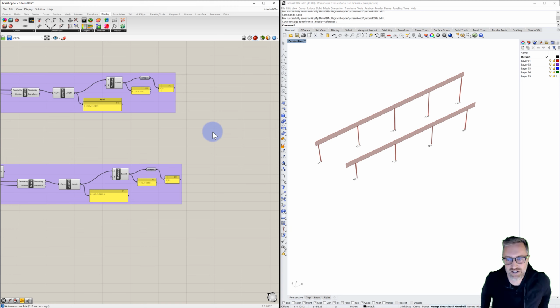Let's put that aside for a second, just because I want our structural model to just look pretty clean and simple. And so as we divide each length, we see that there's a different amount. If we were to simply divide one of them by 27, the other one by 23, we would have to deal with those 4 extra divisions and what would happen with that, right? These could all run parallel at 24 inches, but as we got to the end, then they'd space out and they would come to the last point here. I didn't think that that looked very good. And so what I'd like to use is to decide one or the other.